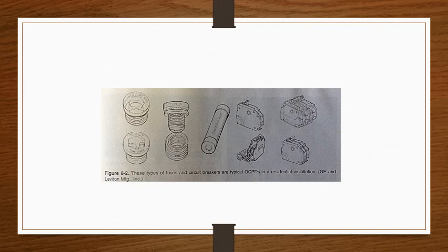Never replace fuses or breakers with protective devices of a higher amperage rating than the one intended for that circuit. If you do, you defeat the purpose of the protection device, violate the codes, and create a fire and shock hazard.